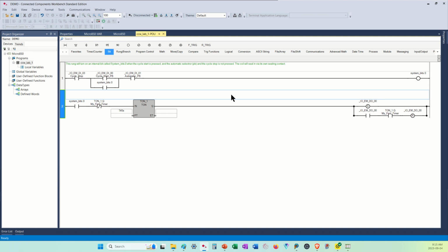Now, in our toolbox of programs, we actually have one that does that. It's called a TONOV, a time on and then off, and is specifically designed to do what I'm trying to do, which is to make a flasher. There's another way we can do this, and what I want to do is I'm going to take this branch, highlight it. Now when you delete a branch, be careful where you highlight it, beginning or end. Take the end and press the delete key. Poof, there it is gone.